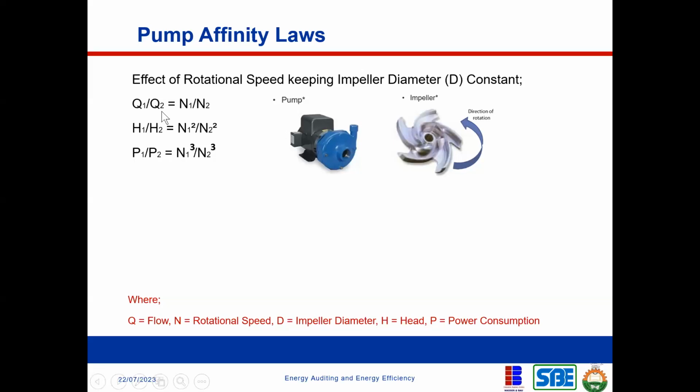So the first affinity law says, now, remember I talked about the impeller, which is the main component of a pump, right? Now, an impeller has a diameter, from this end to this end. You can increase the diameter, you can reduce the diameter. You will believe me that if you increase the diameter, you have more flow. But having more flow means that you have to add more power to drive it, right? So affinity laws help us to understand the relationship between all of this. Assuming that you keep the diameter constant, how does it affect the energy that is drawn? How does it affect the quantity of water that is delivered?